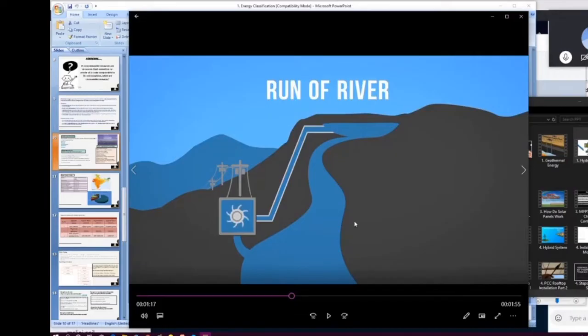So when there was a blackout, all the auxiliary powers were switched off, so there was no power supply. What was done is the pumped water station pumped the water from the lower reservoir to the higher reservoir to generate electricity, and that way they started the auxiliary powers and ultimately all the thermal power stations. Next, which we are seeing here, is basically a runoff river.